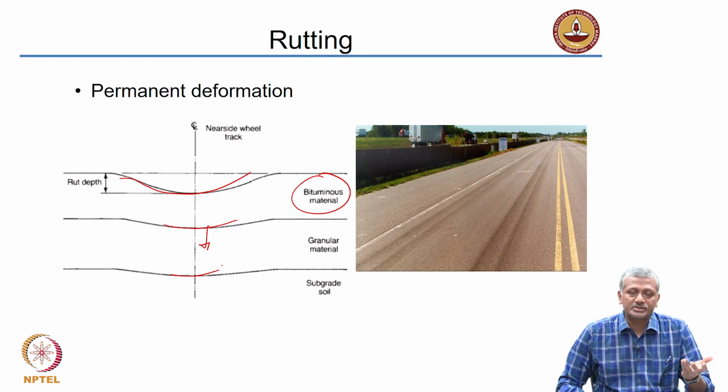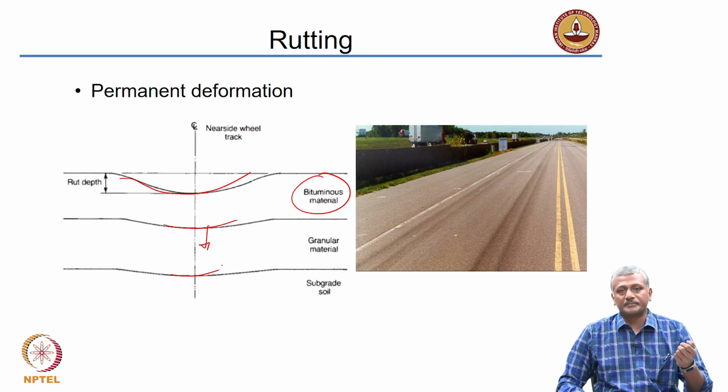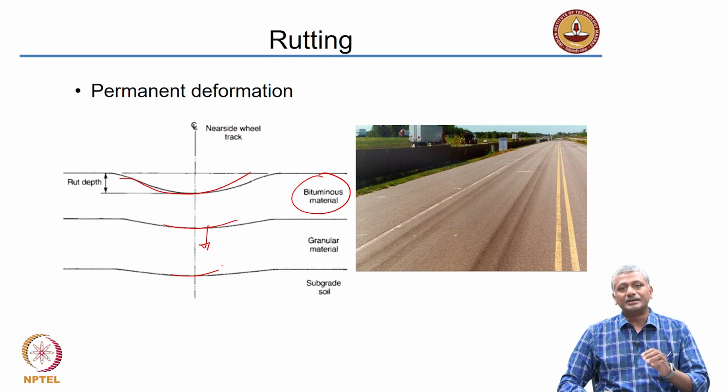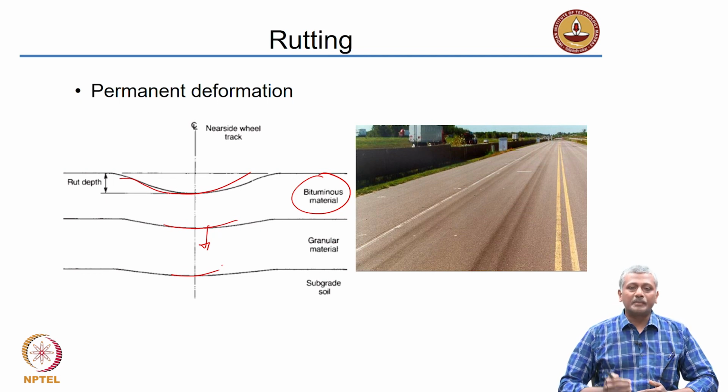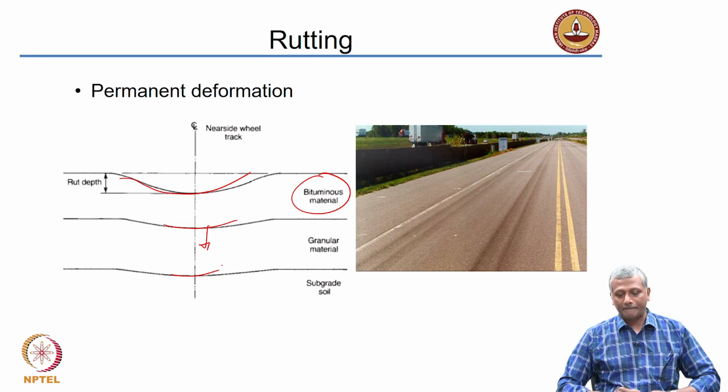Sometimes when the ambient conditions are 40 degrees Celsius, the temperature of the asphalt pavement can be as high as 60, right. So, because of this aspect, you need to ensure that you consider not just the ambient conditions, but what could be the temperatures which may happen in the asphalt pavement beyond the ambient conditions and design adequately for that.